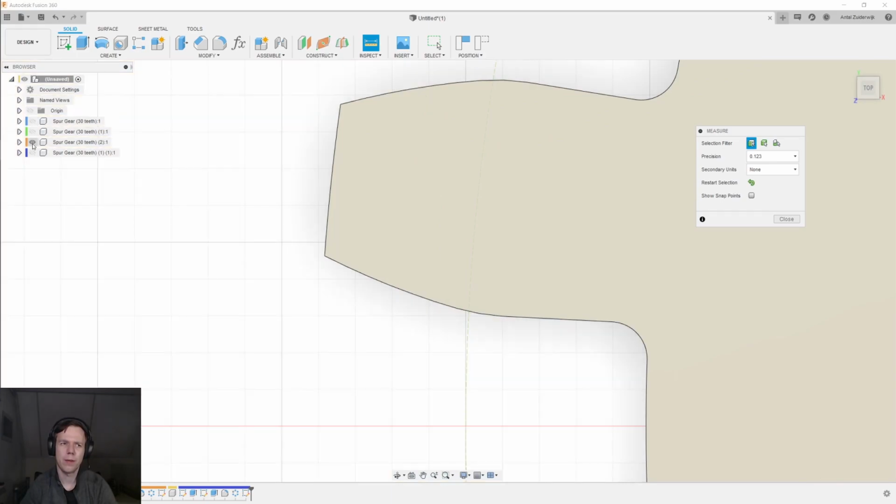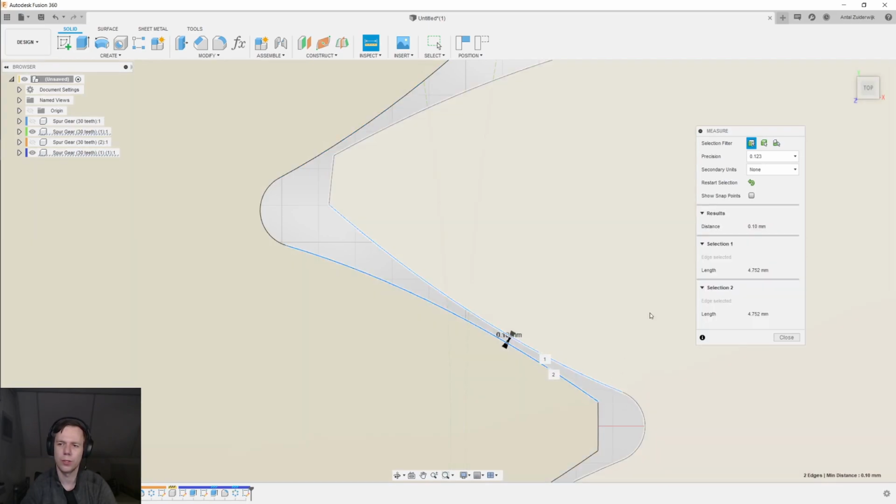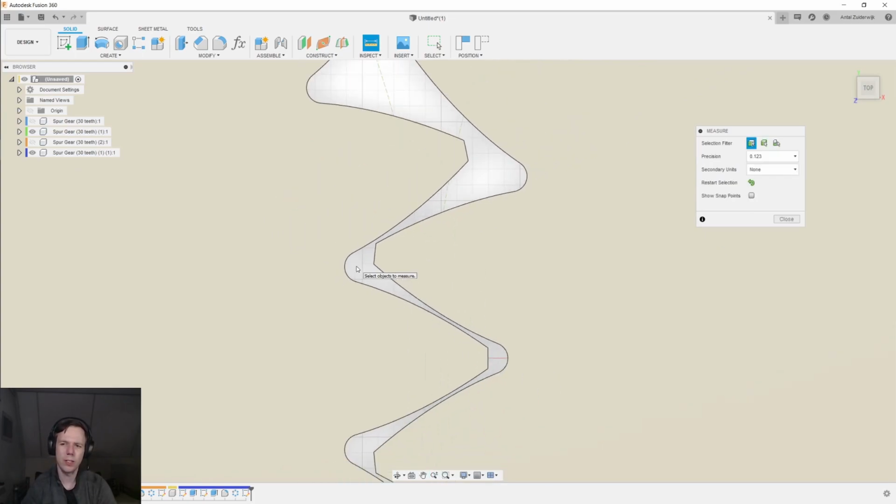And if we compare that now to the same distance but for the 30-degree pressure angle gear, we see here a distance of 0.1 millimeter plus a little bit, and on the other end we also see 0.1 millimeter. And so that distance is a lot larger than it is in the other case for the lower pressure angle. And so what we see here is that a slight deviation in shaft-to-shaft spacing has a much larger effect on the backlash if the pressure angle is larger.